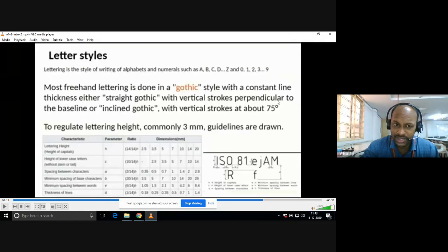For titles, for example, I am putting a main heading, right? For the main heading you can use 7 mm height lines. Within that 7 mm height, you can write any capital letters. So we are not giving much importance to letters and numbers. Our intention is to prepare technical drawings. However, if you are interested, go through any standard textbook. You can find the standards and you can also use them. But see that there must be no wastage of time.